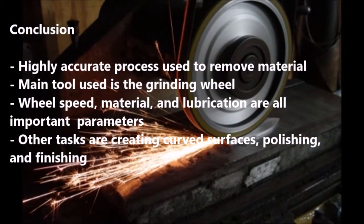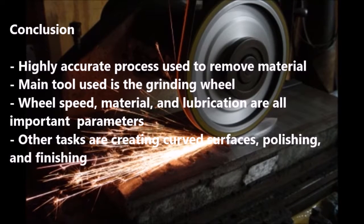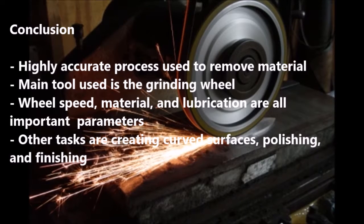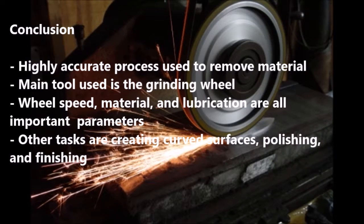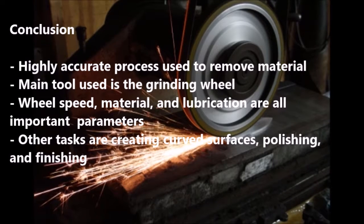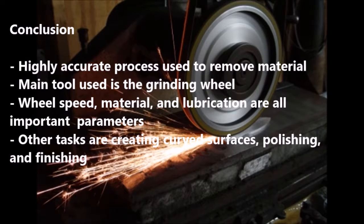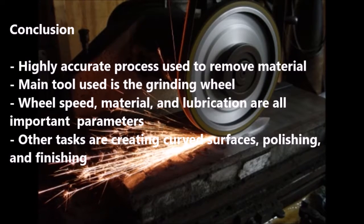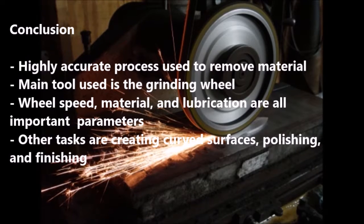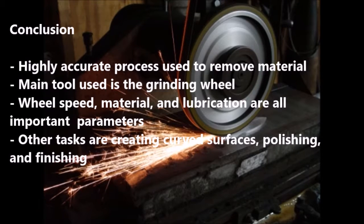Grinding is a highly accurate manufacturing process used to remove material and create smooth finishes. This is done by a hard, rotating abrasive grinding wheel making contact with the workpiece. Important parameters that add to the quality of the process include wheel speed, material, and lubrication. Some significant types of grinding are surface grinding, cylindrical grinding, centerless grinding, and creep feed grinding. Overall, this manufacturing process can be used to create curved surfaces, polished parts, or finished products that require tiny tolerances.